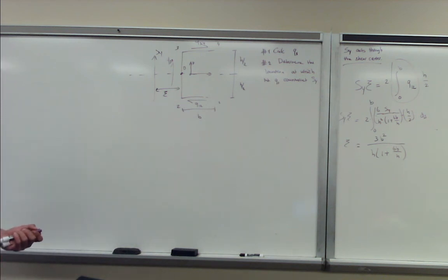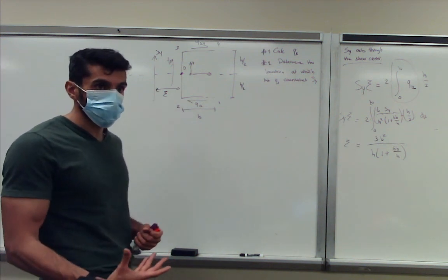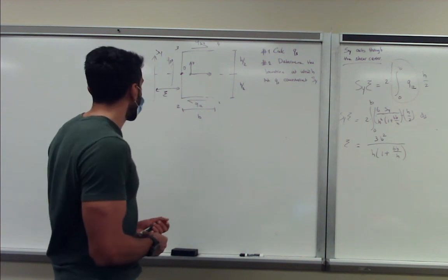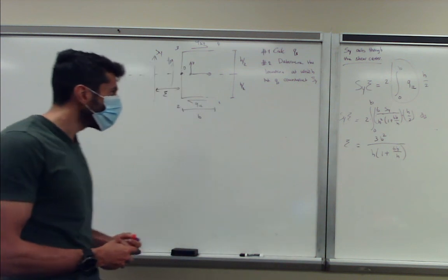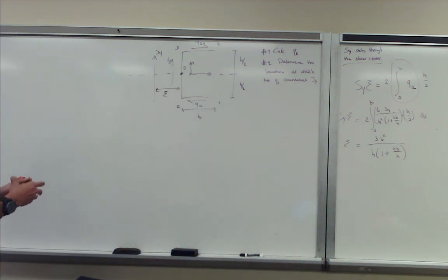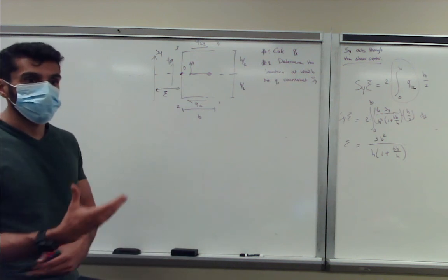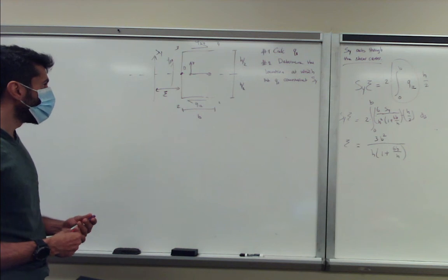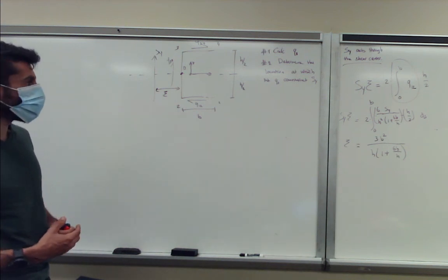We also know that our shear force causes internal shear flows. At the end of the day, those two have to be in equivalence to each other. So once we calculate the shear flows caused by our shear force, we can ask at what point these two equal out. To do so, we do a moment equivalence study, or moment equivalence equation.